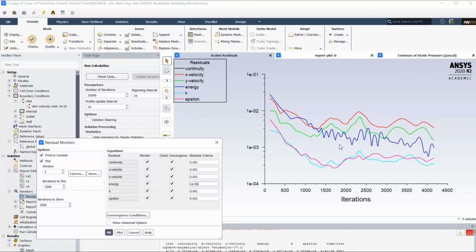And because of the change of the type of the differential equation, the method of solution is completely different. So the program is switching from one method of solution to another method of solution, from one step to another step, and back, going one method, another method, then returns back to the first method. There is a specific point where it happens on this shockwave transition, and from a computational point of view, it generates small perturbations.